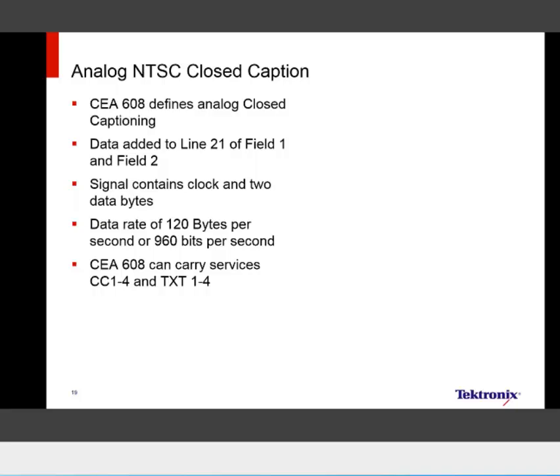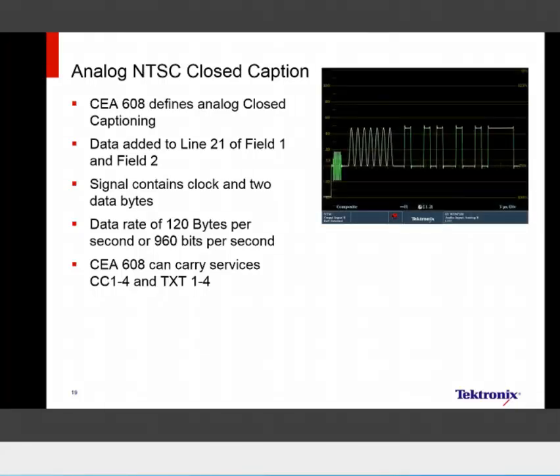In the old days with old 608 captions, it was fairly simple to verify that our captions were in and correct, because we could go to line select on a waveform monitor, walk back to the 608 captions, and verify that the run-in was in the right place, the sine waves in the beginning, and that the timing between the leading edge of sync to the center of the leading edge of the run-in was absolutely correct. They were 50 IRE, sitting on the zero line on the bottom going up 50 IRE, and if we met these criteria, the captions would be displayable on any decoder there was.